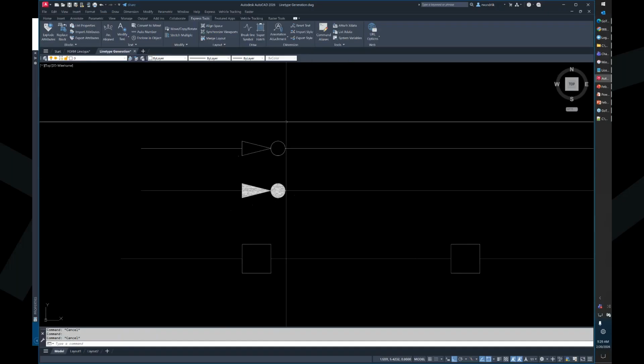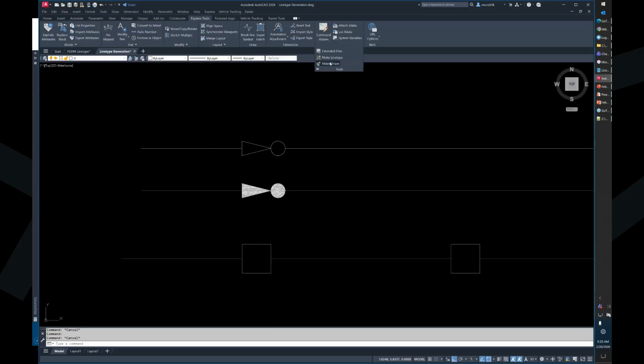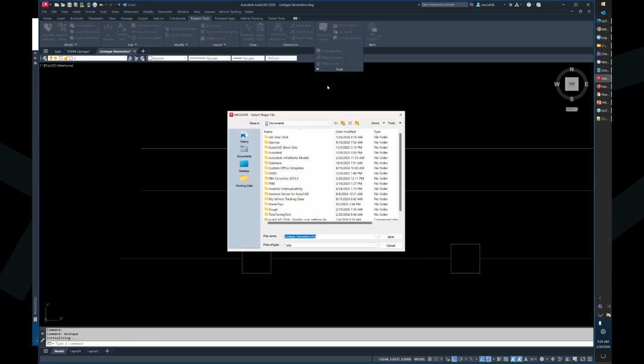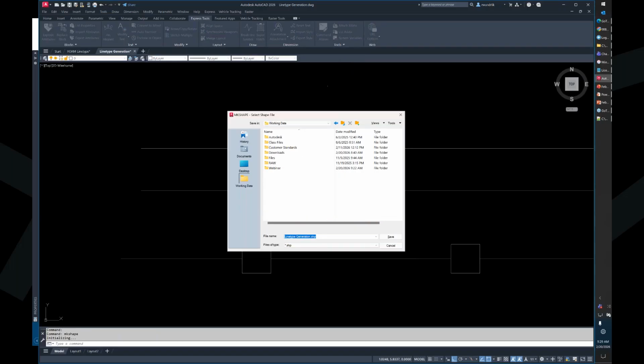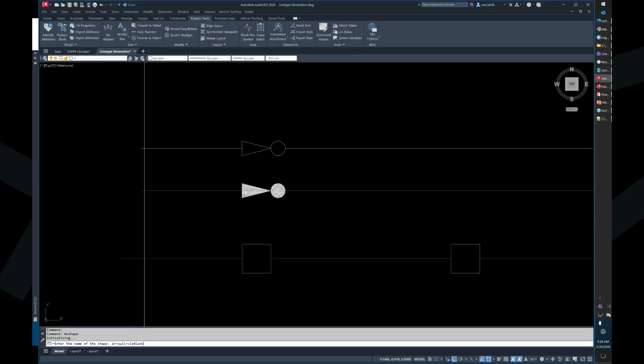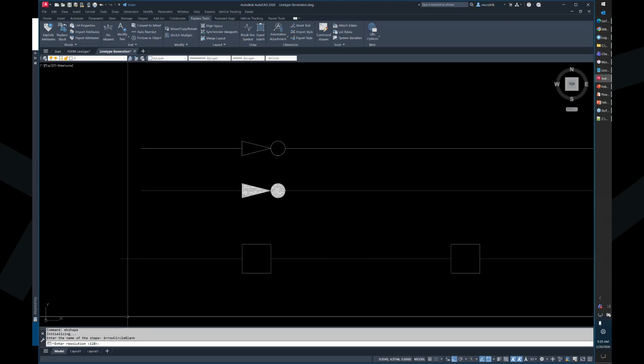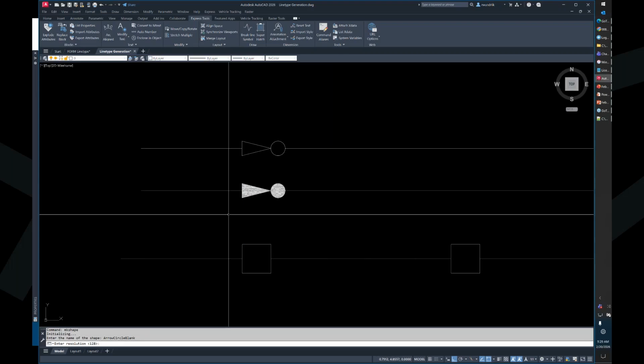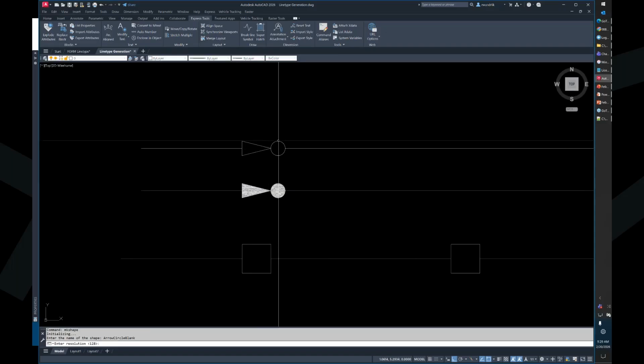Again, we just come in here, go to tools, and make a shape. I'm going to copy this because I like to do that. Enter the shape name, arrow, circle, blank. Enter the resolution, 128 is fine here. If you have complex geometry, especially things with a lot of curves, I usually like to make that 4096.